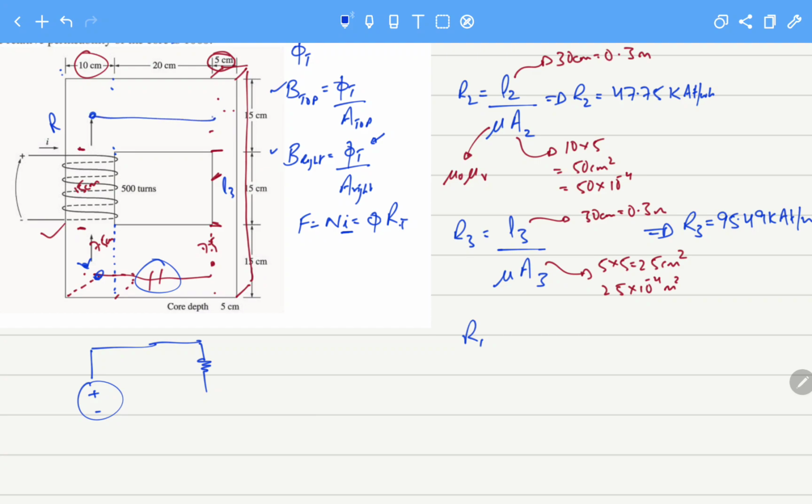So from the top of the core, the distance is actually 27.5, and here we can see 5, then 20, then 2.5 up to here, 27.5, and if I combine the bottom part also, it is 27.5. So this will become 55 centimeter.